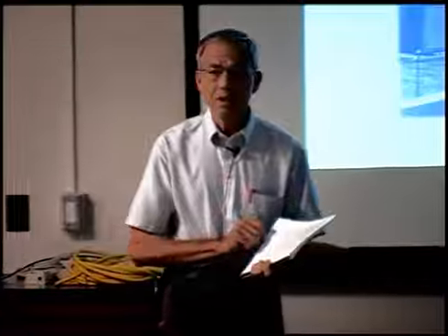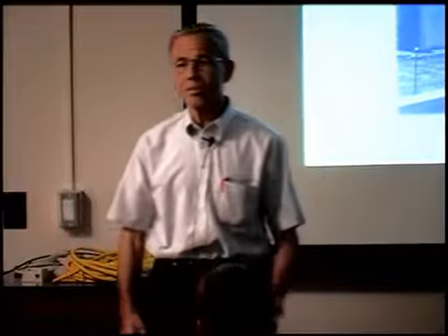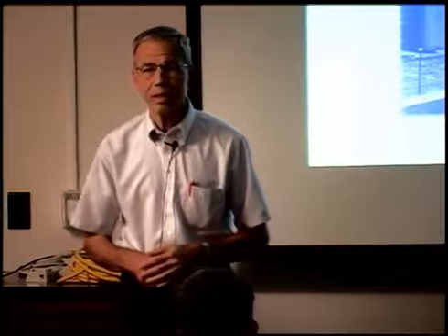That number, as I believe was mentioned by one of the other speakers, is really just our 0.725 rounded to an even fraction. Also, we have an example in your volume 4, starts on page 60, which is a case where the pile is driven to rock. And not only that, but we're picking up some friction up above the rock. So it's got both the friction above the rock as well as bearing on rock.